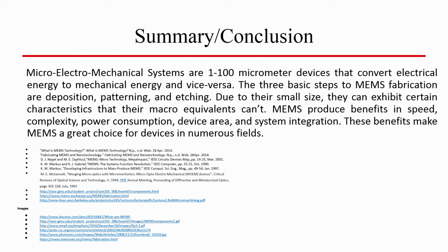So, in conclusion, what we have understood about this particular lecture, which was focused on MEMS, is that MEMS are systems which are in a 1 to 100 micrometer range, and that can convert electrical energy to mechanical energy and vice versa if you are talking about piezoelectric. But if you are talking about piezoresistive, then you apply pressure, which is mechanical energy, to get a change in resistance, again mechanical to electrical. The 3 basic steps in MEMS fabrication are deposition, patterning, and etching, right.